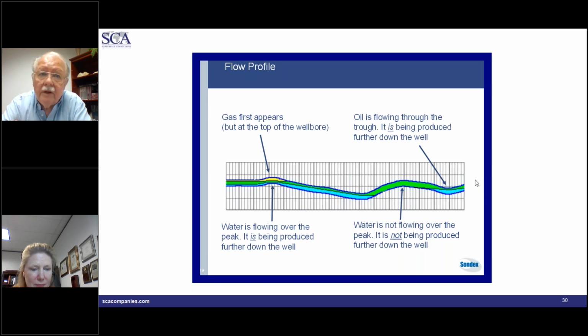Not the production logging tools. The production logging tools would basically see what's coming in at each perforation. Now, the pulse neutron tools would be used typically to find those water oil contacts or water gas contacts. So the pulse neutron would look out in the casing. It would tell you what fluids are out there. Then what you have to do is look at what's being produced and make sure the two correlate with each other. Because if they don't, that means that perhaps you have something coming in through a channel.